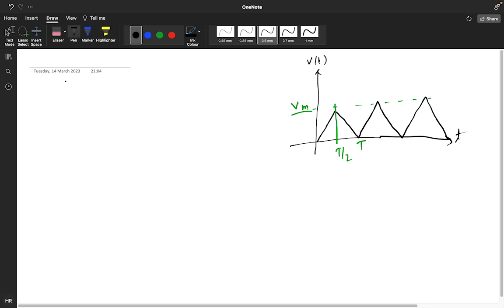So guys, the formula for the RMS power, Vrms, is root under 1 by T, integral 0 to T of V square of T dt. So guys, for this triangular signal, how will you find the RMS power? For this you have to know some basics.